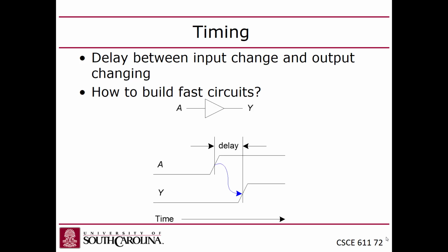So, for example, there's A. A is low, 0, false. And then at some point, it goes up to true, right? At what time? At this time. When it gets about halfway between false and true, that represents the time at which we consider it to have transitioned. You guys with me? So what's that time? Well, you have to go all the way down to the time axis and figure out what time that happened. But it happened right here.